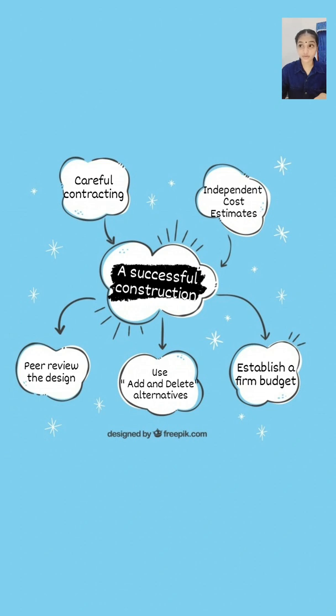Owner draft contracts frequently seek to protect the owner from all possible claims. Such contracts contain exculpatory language, waivers, and limitations intended to bar virtually all claims by the contractor. The idea is to protect the owner from all foreseeable and unforeseeable risk by shifting responsibility for those risks to someone else. One-sided contracts, however, may generate as many claims as they prevent.